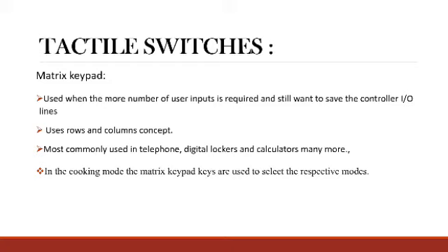The tactile switches are used as a matrix keypad when a larger number of user inputs is required and we still want to save the controller's input or output lines. It uses the rows and columns concept. Most commonly used in telephones, digital lockers, calculators, and many more. In the cooking mode, the matrix keypad keys are used to select the respective modes.